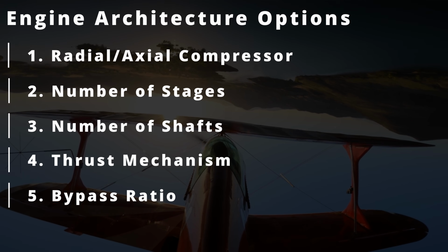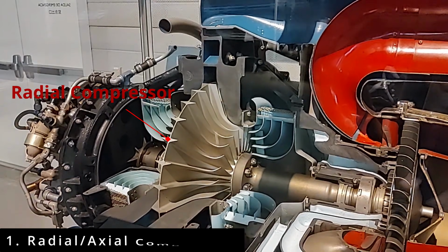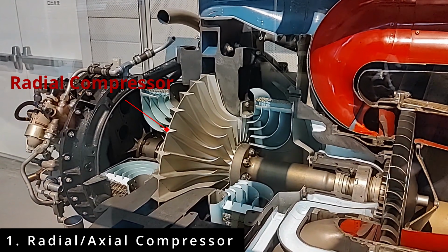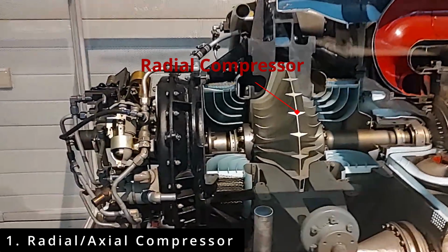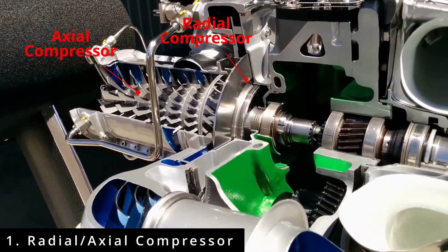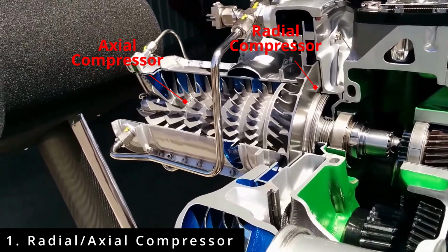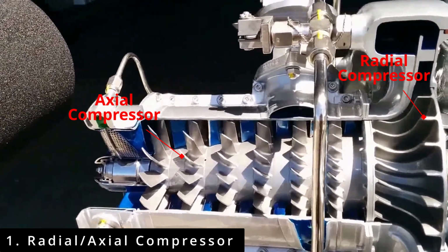Frank Whittle's engine had a radial compressor, meaning that the air is spun outwards and compressed. This is a good solution, but results in an engine with a large diameter. Enter the axial compressor, first run in 1940. This compresses the air in the same direction that it's flowing.